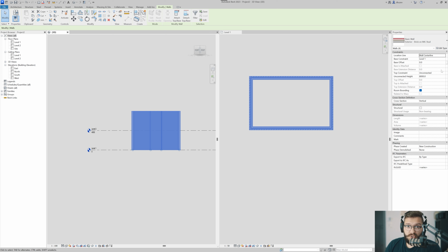Now, to us, this is okay, but if we have a project in which my exterior walls go from a certain level to another certain level, I may want to constrain that to something. So I would say a top constraint, put it at level 2, boom, good to go. Does that mean that I cannot surpass it? Absolutely not. One of the things I can do right away is do top offset. So let's say I just give it 1000 or 1 meter. In Revit, if you're a newbie, hi, you can just type 1M and hit enter. So this would automatically set 1000 millimeters.